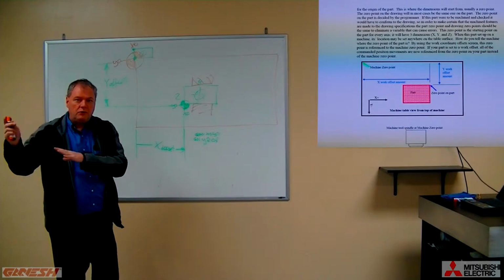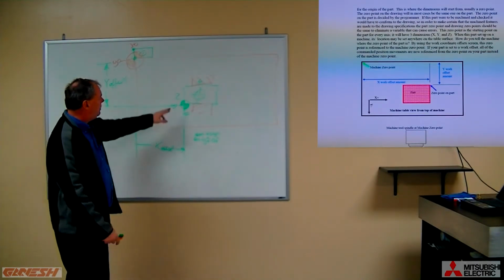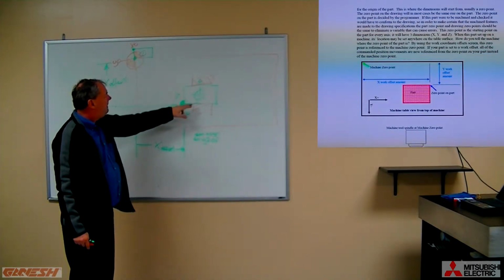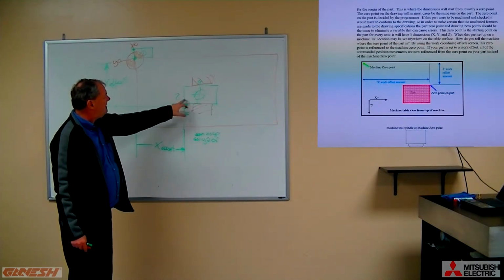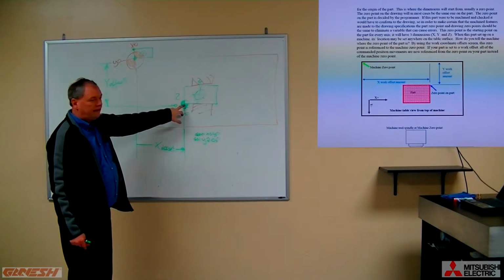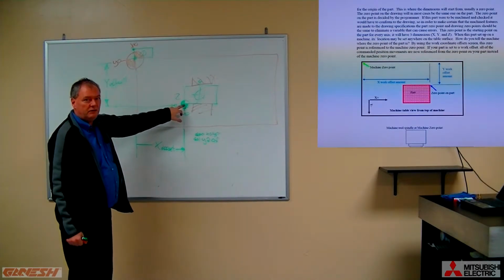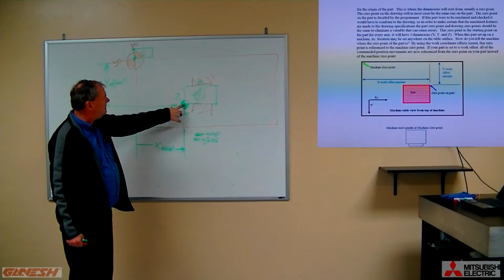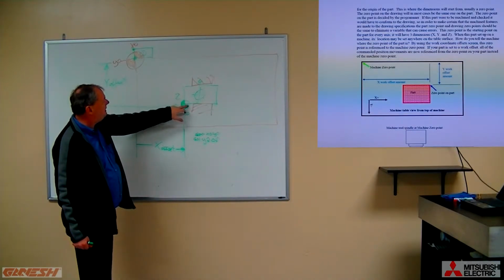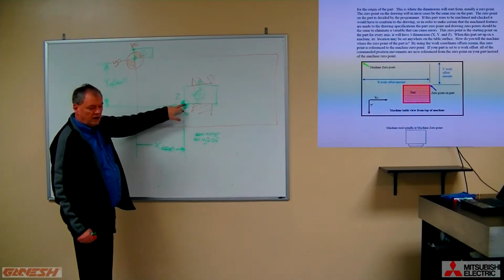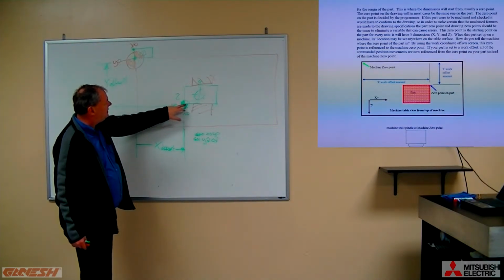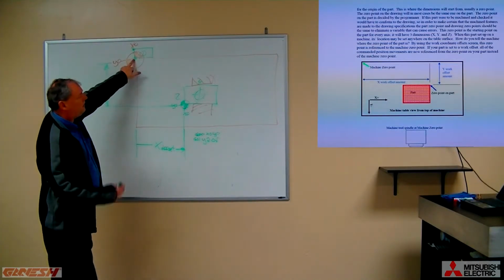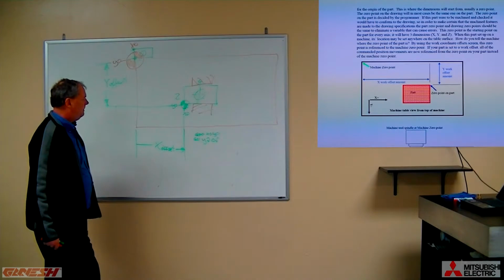Your operator, or you who are setting up the machine, will indicate this corner. If this is the hard jaw of the vise, you will indicate this edge and that edge, and you will get a number, which we demonstrated to you out on the floor, on the control. You're going to locate where this corner point is in relation to what we call the machine coordinate system.